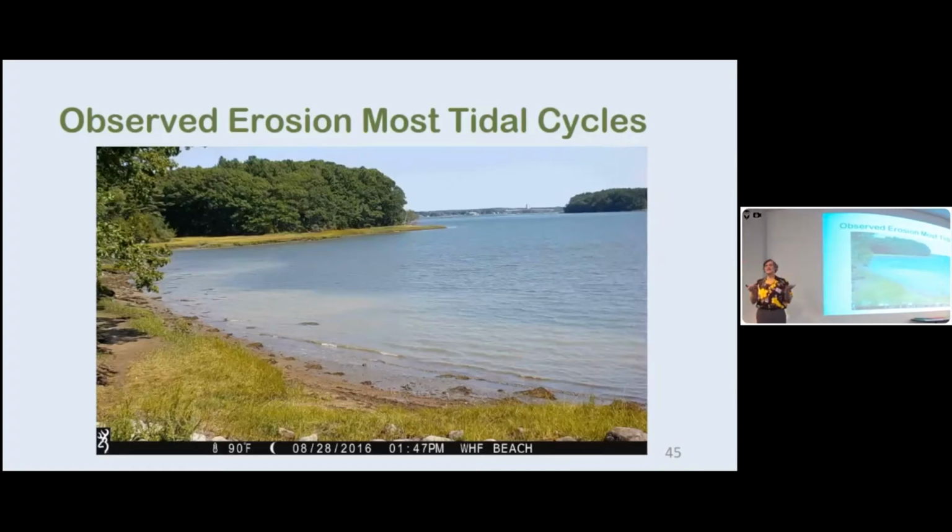It's relentless. A lot of our shoreline has the peat, which has the plant roots in it, and it's very resistant to erosion. But below that is an incredibly soft clay. So classically, what you see along the Great Bay is undercutting, collapse, and then either rafting out of the collapsed material or just wave attack, bringing that material out into the Great Bay, and then the process starts over again.